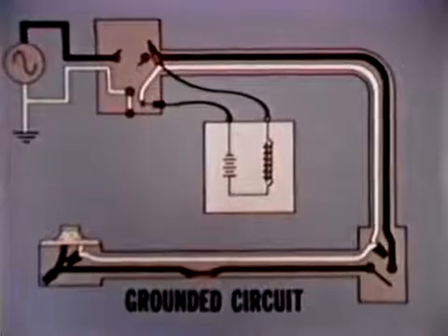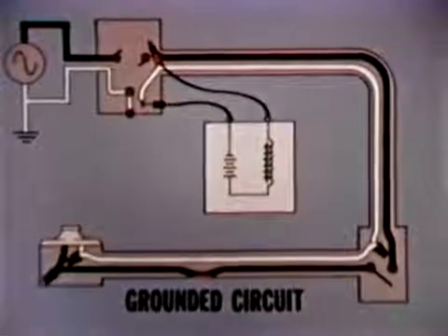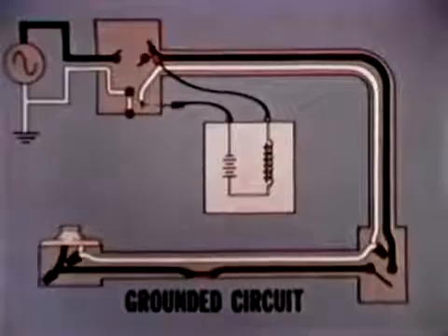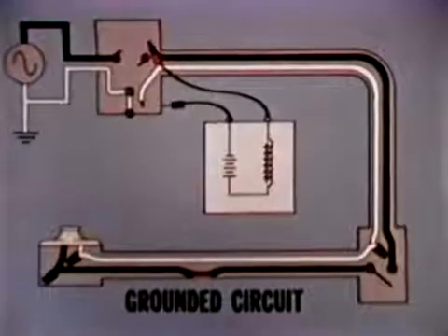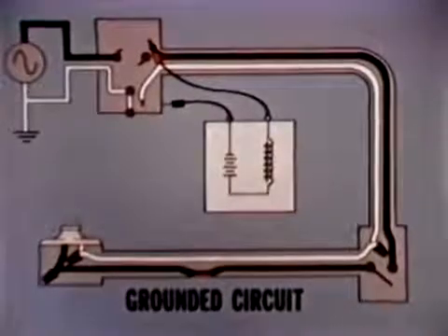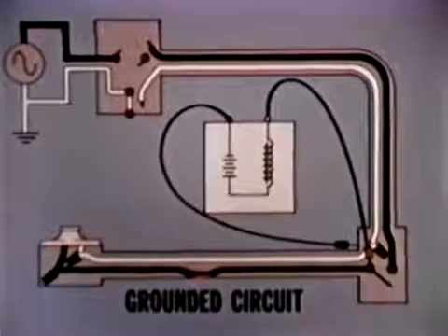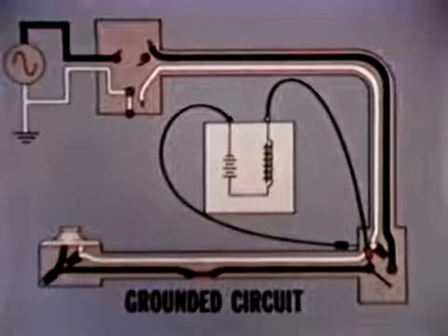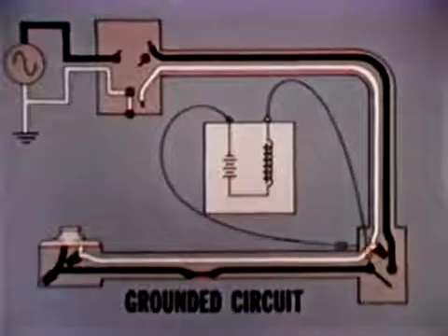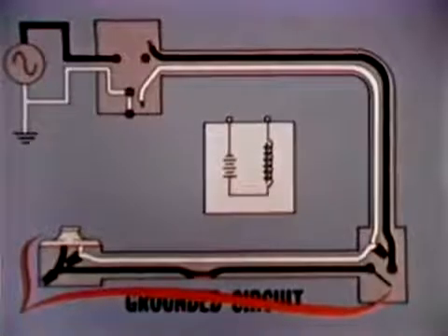First, checking between the two conductors indicates that there is no short circuit in the first section of the circuit, and there is no continuity between the hot conductor and ground in this section. However, between the hot conductor and ground in the second section, there is continuity. Since this is the last section, the testing is complete.